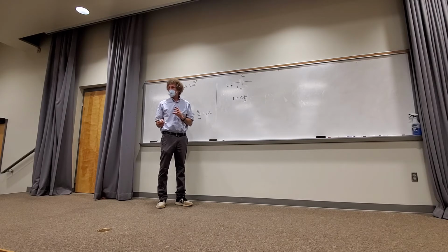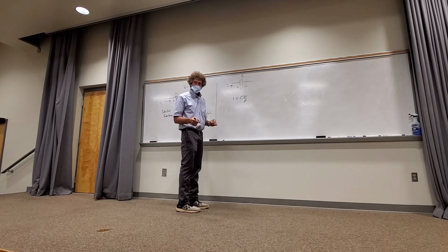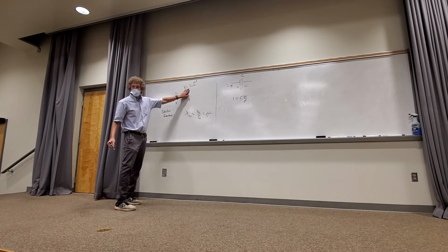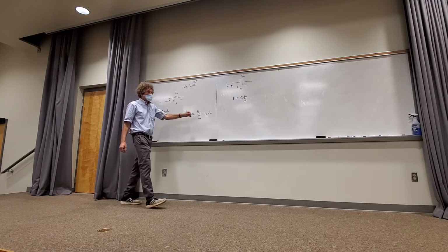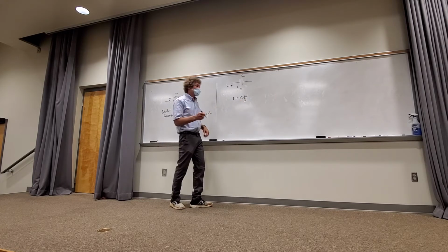You with me, class? Now, when we do the same thing here, we assume both voltage and current vary as e to the j omega t. Here's the real thing that happens. Every time there's a time derivative, a j omega pops out, and the e to the j omega t goes away. So we don't keep on doing that over and over again.